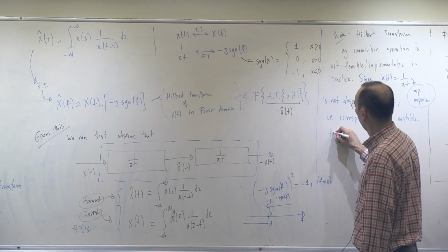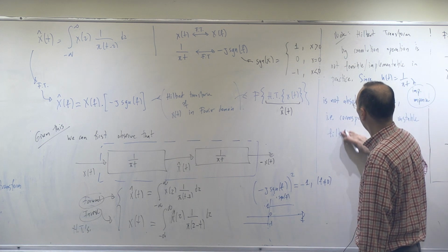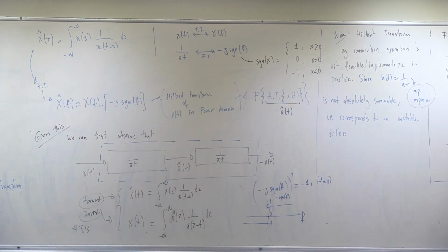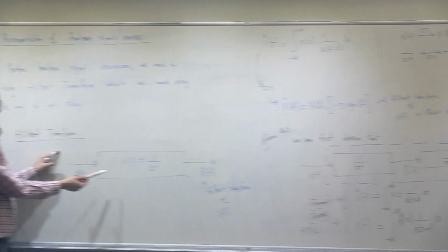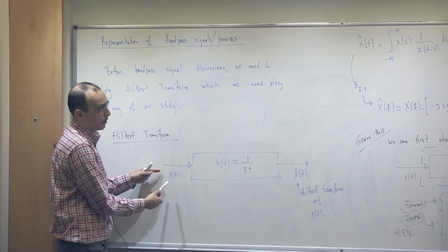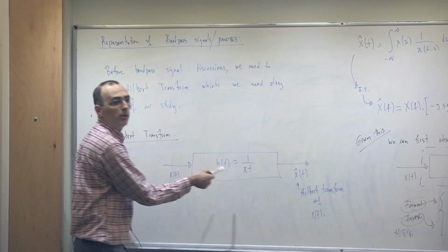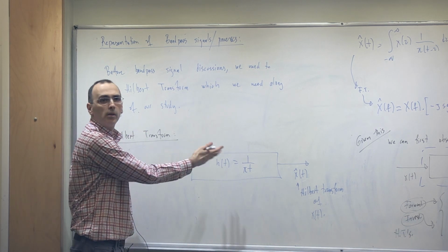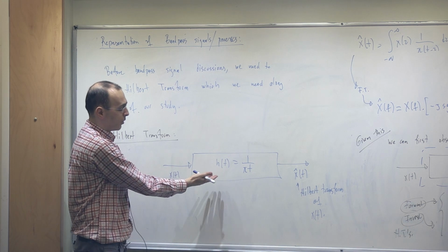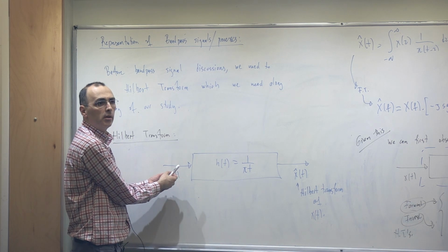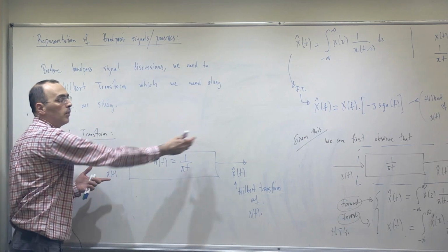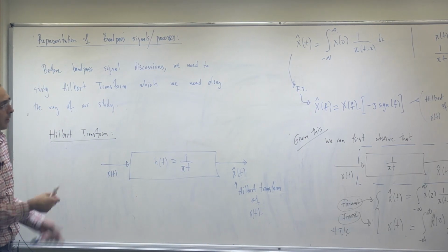Terrible news. Unstable filter. So what do I mean by that? If I design a filter like this, now this is an unstable filter. If I process this, I'll be getting some output, but due to the filter being unstable, there is no steady state, that kind of concept over here. So if there are some uncertainties or mismatches, some noise effect, it will significantly affect the output because the filter is unstable.